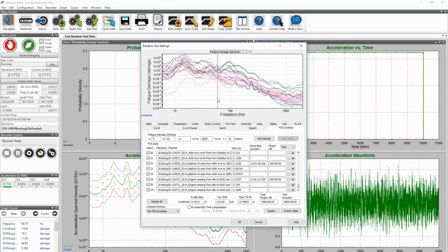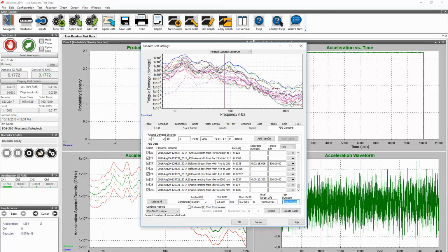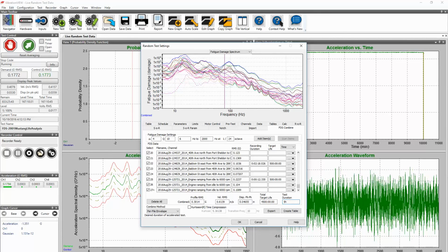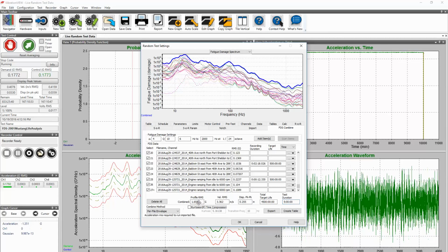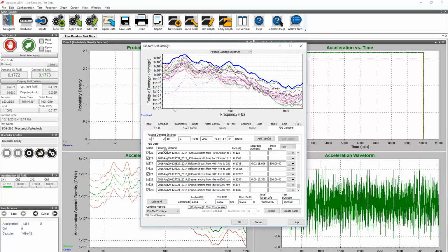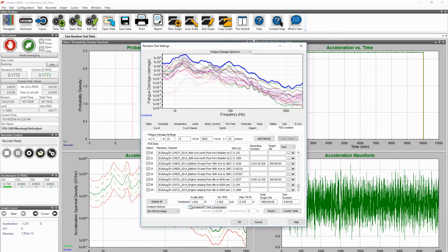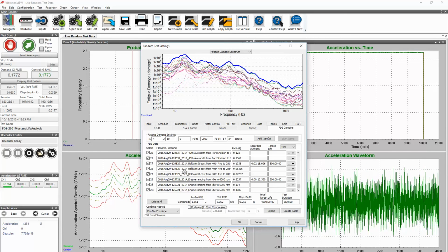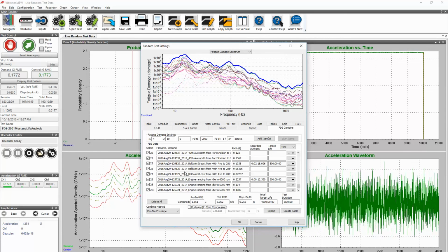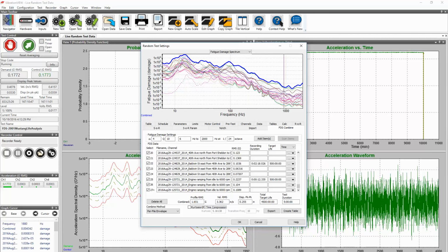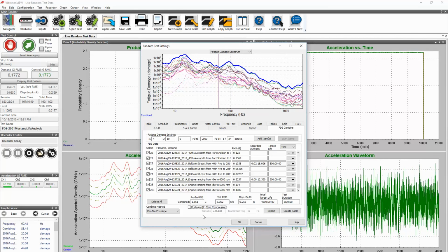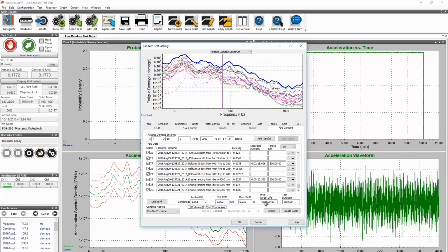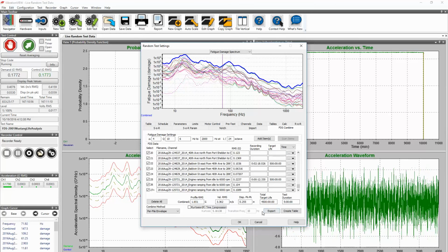Now this is outside the scope of what we want to do, but just a quick comment. Typically you would maybe want to run this for 5 hours. So instead of 0.3 G's, you're going to see that it looks at the M and the Q and says, okay, run it at 1.6 G's for 5 hours. That will give you the same amount of fatigue as all these individual ones summed up. But in our case, we are interested in the fatigue damage of 500 hours of each situation.